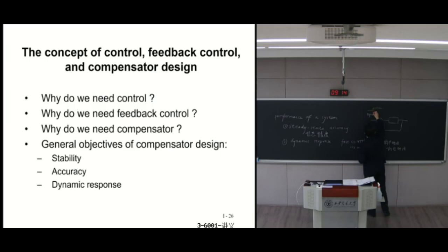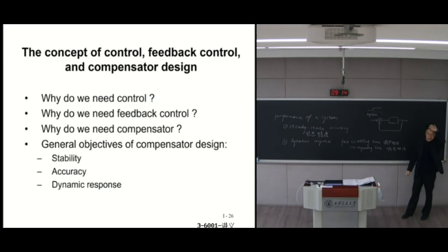Before this point, both reference and output stay at one specific point, and when there is a step change in reference, the output follows the reference to another value, and this responding time represents how fast the output responds to the commanding signal change.